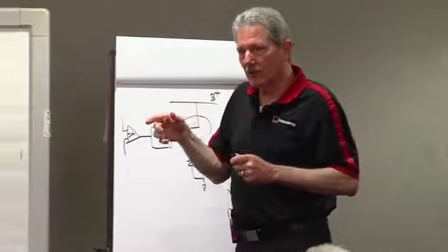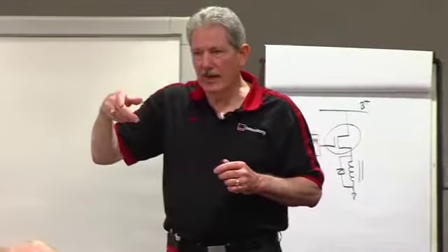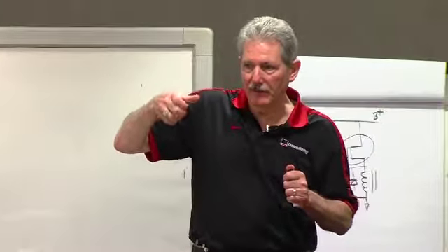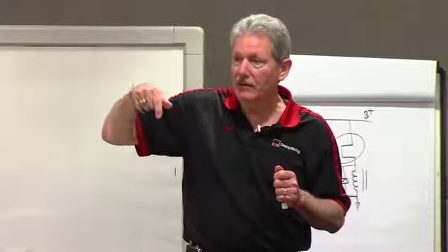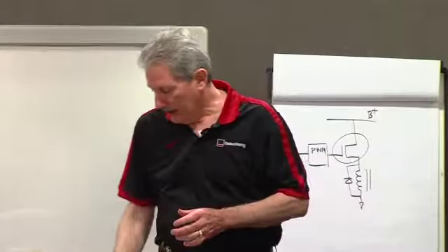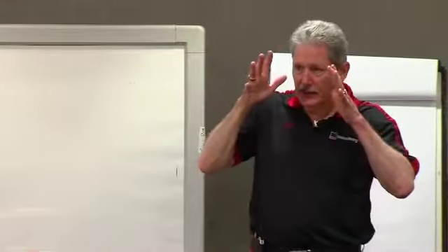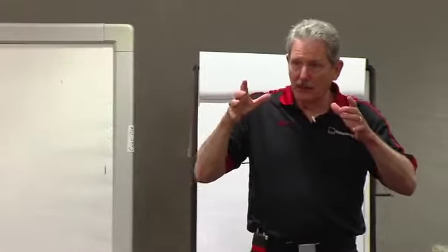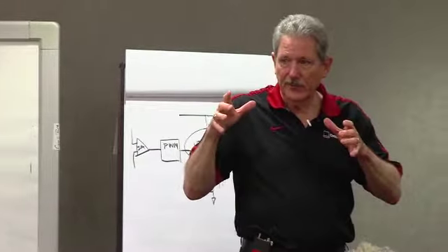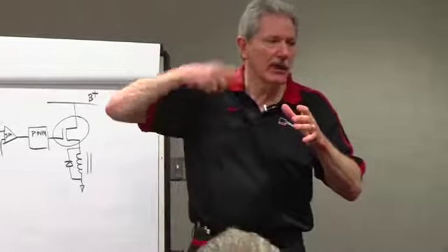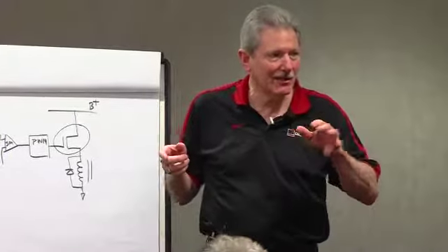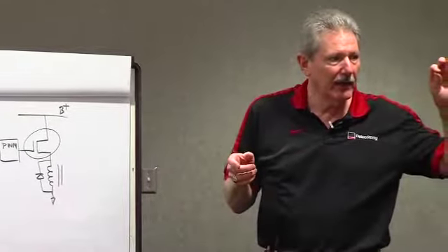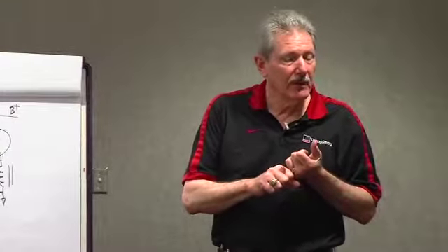Remember what I told you earlier, when you disconnect the battery, the first disconnection is the ground? Look at, for safety reasons, the alternator now. The whole alternator is at ground potential, with the exception of a very small area, and that's the field.